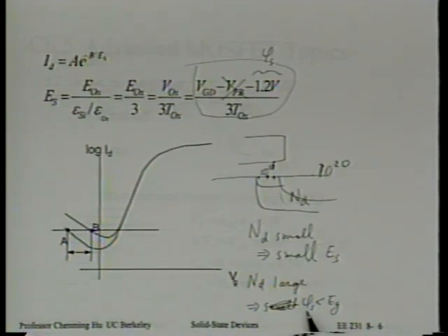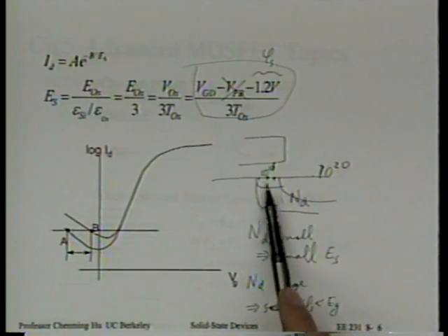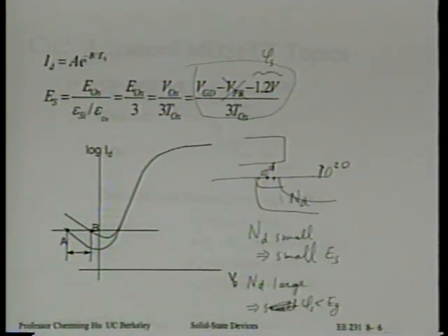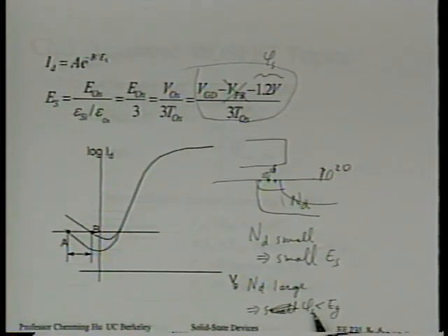Increasing the drain doping is not a solution, because even if we increase to 10 to the 21st, somewhere in the drain we're still going to have 10 to the 18th. You see what I'm saying? Okay. So this definitely is not a solution, right? So here, that's kind of the answer. If you truly don't have any overlap, there's no GIDL. But if you have LDD, you say, you know, I still have some drain, not so heavily doped.